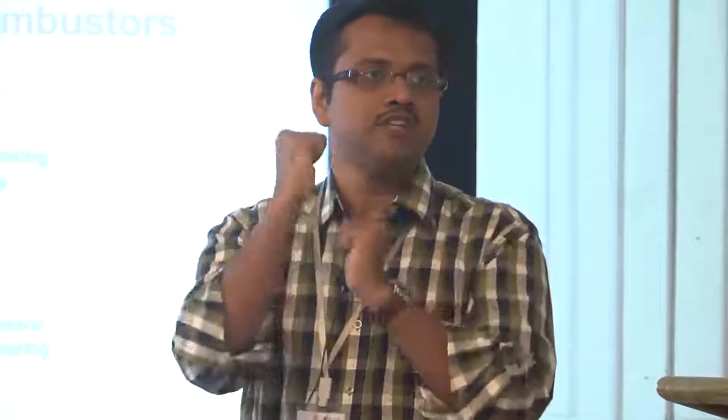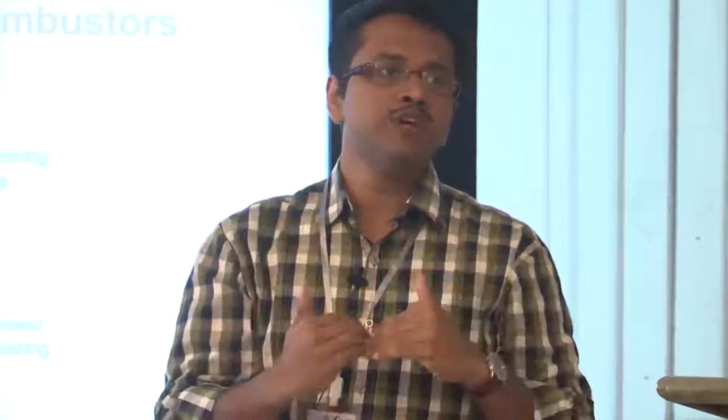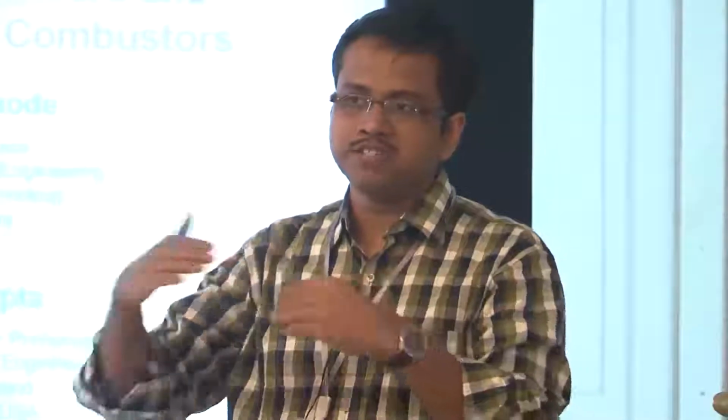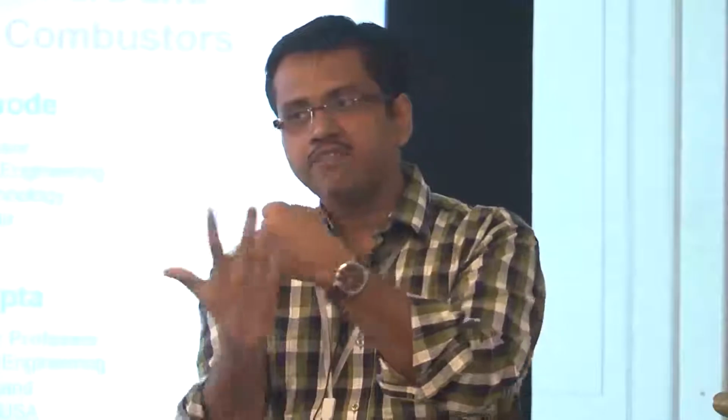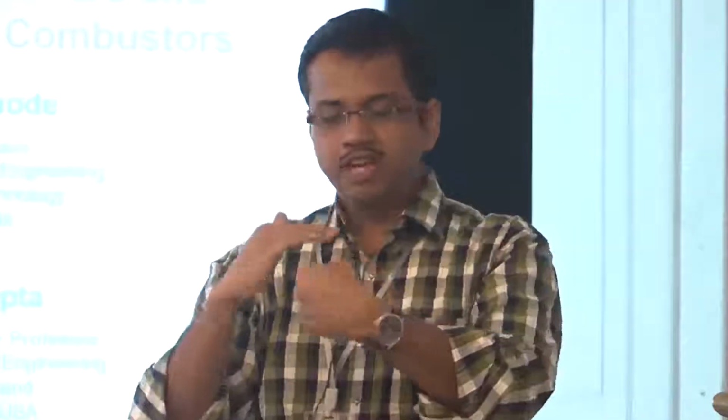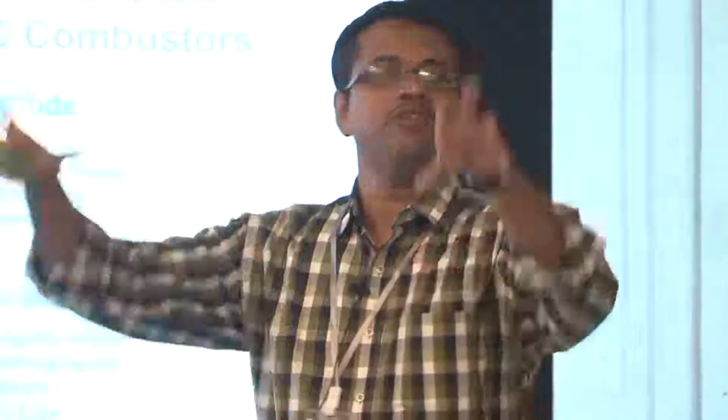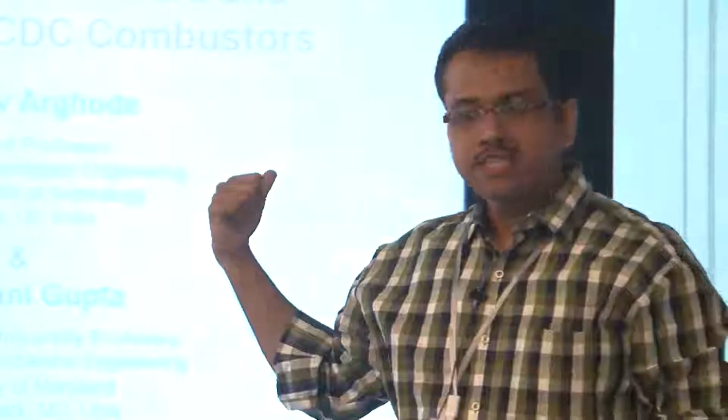The Rossby number is basically a toppling kind of moment, because the two streams are moving at two different velocities. So Rossby number equal to 0 essentially means two things. Either both the streams are moving at the same velocity, so there is no velocity deficit along the interface, or it is like the traditional flames that Jackie O'Connor and other people have studied, where there is a bluff body and the swirl comes around it. Therefore you have a wake region, and then the vortex breakdown bubble sitting on top of it. This also has relevance because we wanted to inject